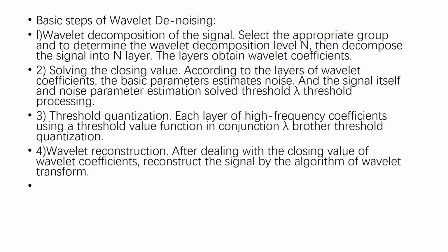Third, threshold quantization. For each layer of high-frequency coefficients, we use a threshold function constructed with lambda for threshold quantization. Then, wavelet reconstruction: after processing the threshold values of the wavelet coefficients, the signal is reconstructed by the wavelet transform algorithm.